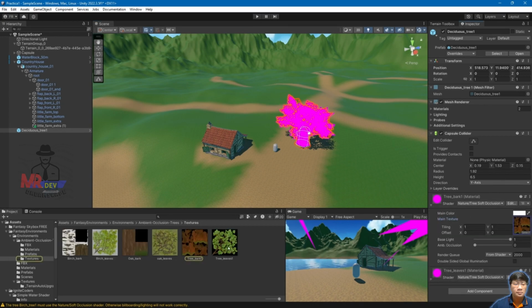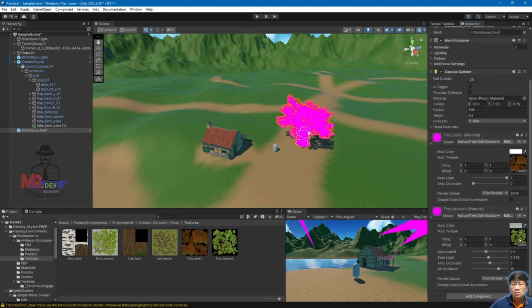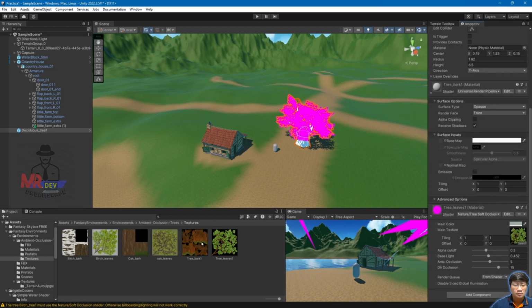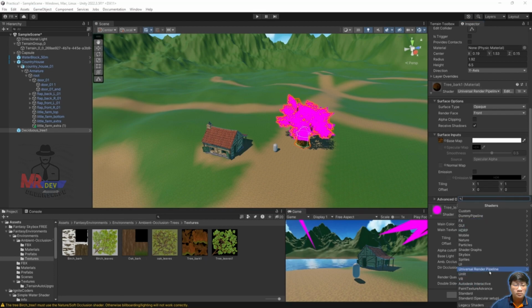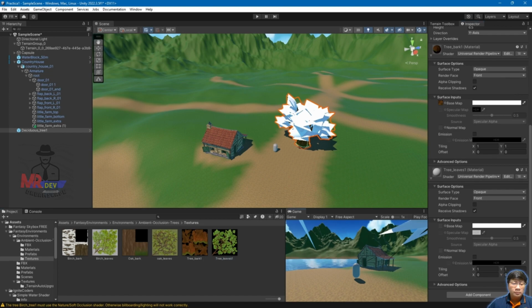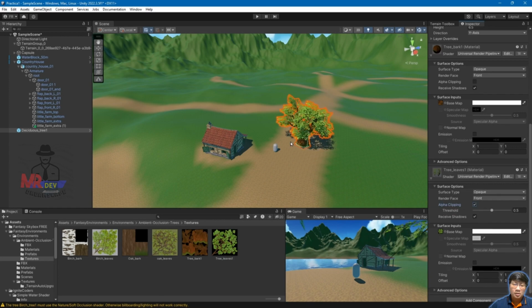We see the texture corresponds to this texture. And these last two would be okay. Then let's change here the Simple Lit shader. And remember that first there was this texture from here. Now we do the same with the one below. Simple Lit, and we are going to apply this one here. Remember we put the alpha clipping on it and that's it.